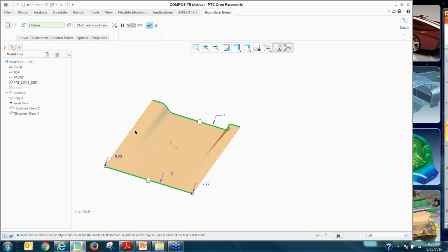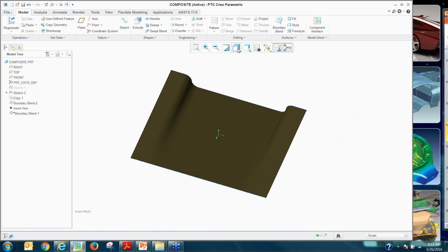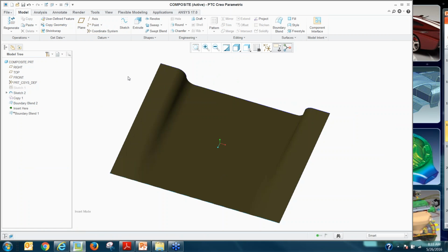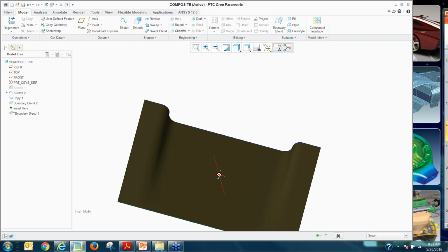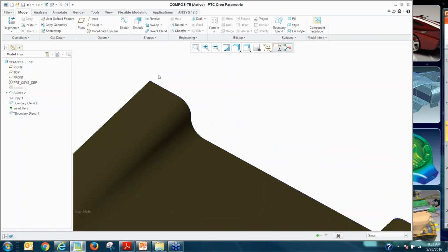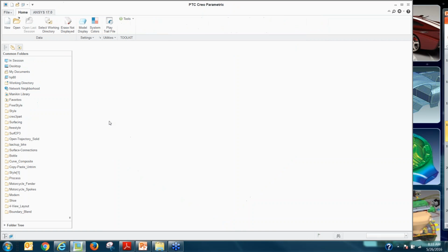you see that I don't have any patches whatsoever, right? I'm in my shaded with edges, and so that's a nice little thing. It's like when you create composite curves, you do have the ability to make it approximate, where it's still maintaining the radius that you want. However, at those connection points between the arc and the line, it's changing the degree in such a way that there is a gradient in the curvature, right? So thereby making it curvature continuous, right?